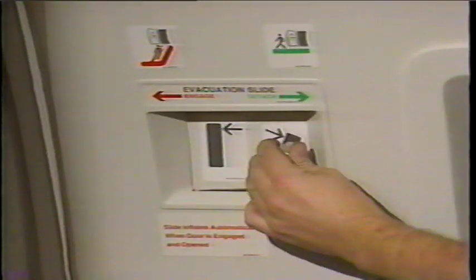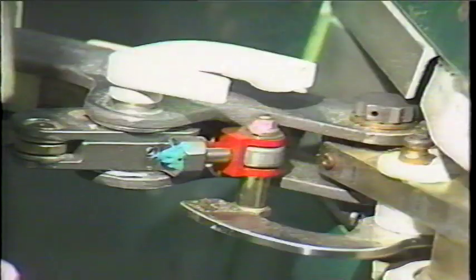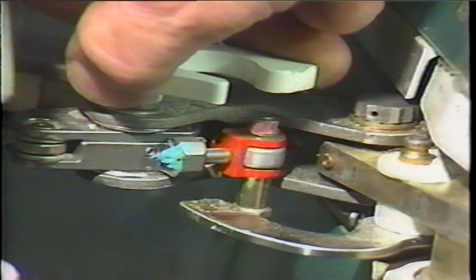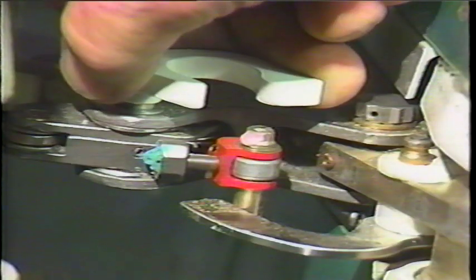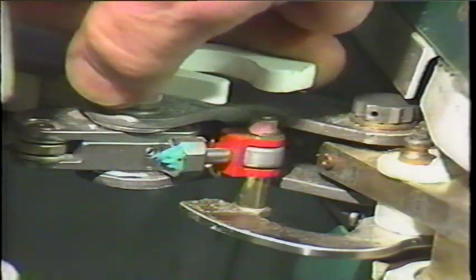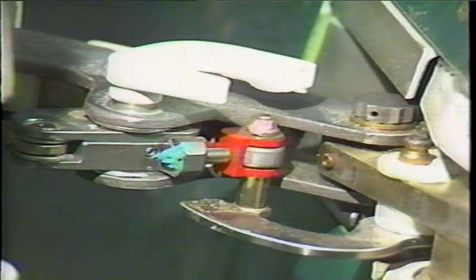Next, check the emergency power system trigger guard. First, perform the detach mode check. Place the door mode selector in the detach position and open the door fully with the inside handle. Try to manually move the emergency power trigger from the detach to the engage position. The guard attached to the upper hinge link on the body torque tube should prevent the trigger from being manually moved to the engaged position.